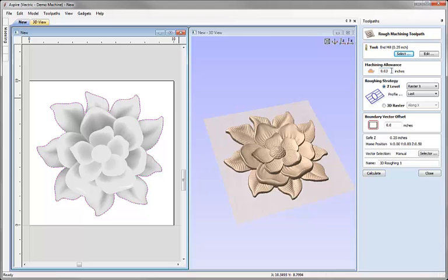Next, within the roughing, we specify what we call a machining allowance. This is an extra thickness of material that will be added to the model so the roughing tool doesn't cut too close to the finished surface. This just gives us a bit of skin that will leave something for the finishing tool to cut, and also tries to reduce the effect we might have of the larger tool chipping our finished part. So here I'm going to enter a value of 0.04 inches, so that'll just leave 40 thousandths of an inch of material as an extra thickness over my 3D object.